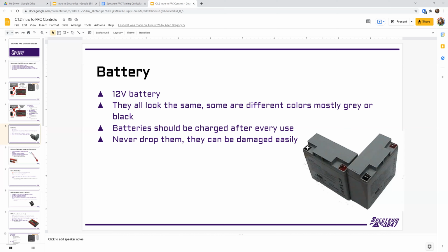If you pick up some batteries and you notice that the wire is loose around the terminal, that's not good. You want to make sure that's a good strong connection there, because if it doesn't move, then you have a low resistance. If it moves a lot, then you have a high resistance between the two terminals, and so you can't get as much current flow out of it. So yeah, we want to take good care of our batteries. They are a potential fire hazard. Once every couple of years, you'll hear about a battery fire or a robot that catches fire.